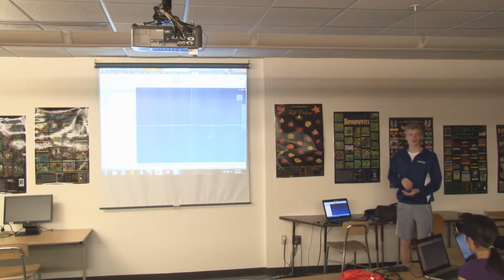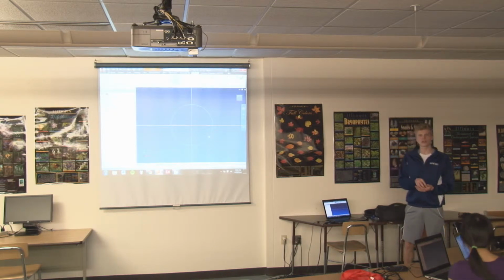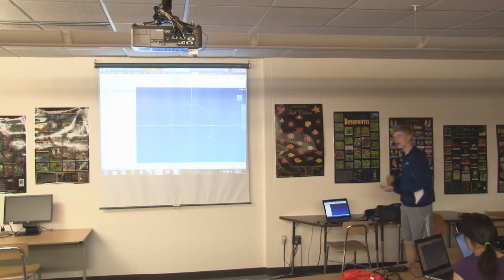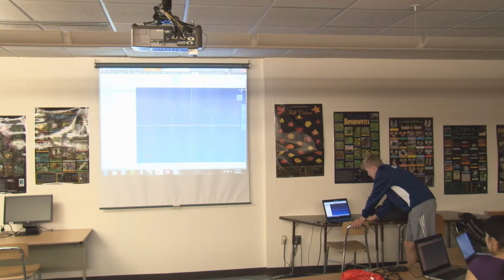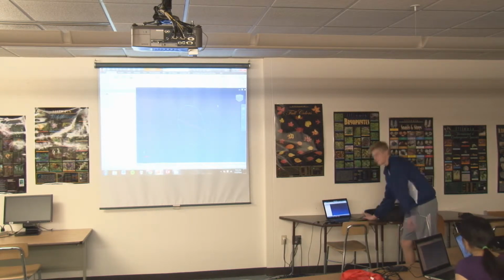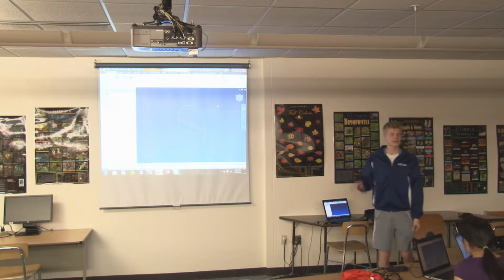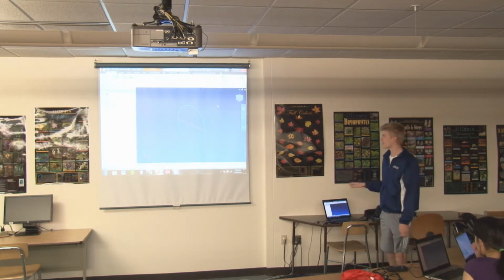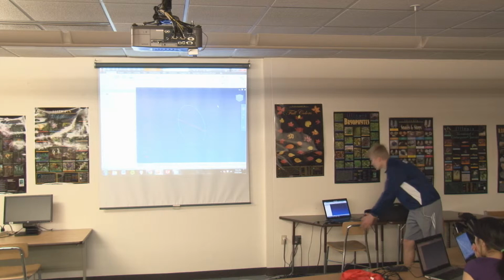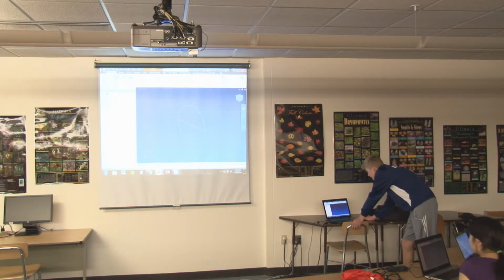And a lot of the creativity comes in from taking that two-dimensional sketch and knowing how to transform it into whatever three-dimensional object you want to use. So click the Finish Sketch button in the upper right-hand corner, and that'll take it out of your sketch mode and bring it back into the three-dimensional view. And then from here, you have a number of different tools that you can use to create three-dimensional structures. Most of the time, you'll use these two tools, Extrude and Revolve.